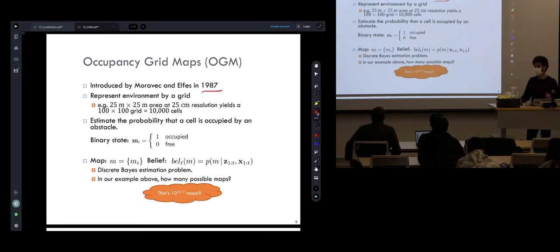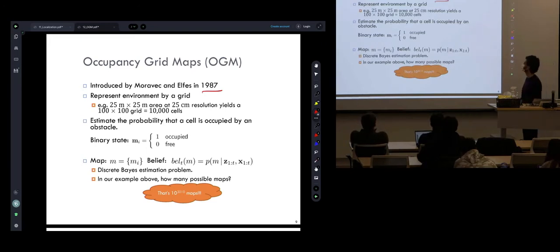So it wasn't solved, because part of my PhD was on occupancy grid mapping, even though I was born in 1987. So I used Gaussian processes to build the same map. That's a regression way of doing it. It's not discrete anymore. Now it's continuous. You can get variance. You get a whole distribution over the environment.